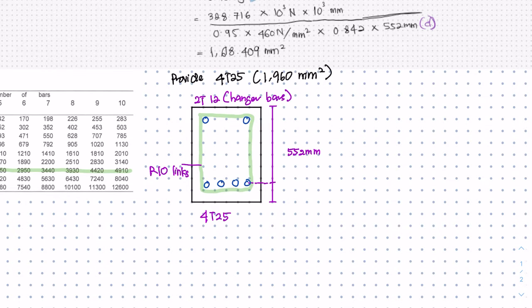So we need to find the balance down here. If the total h is 600 mm, you just minus the effective depth, which is 552. Then you will get 48 mm as the value, the balance at the bottom, after the half of the main reinforcement, you have the balance at the bottom. Right, so we are done with example number 1.